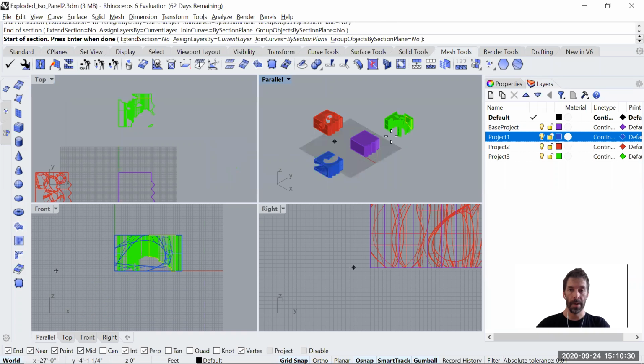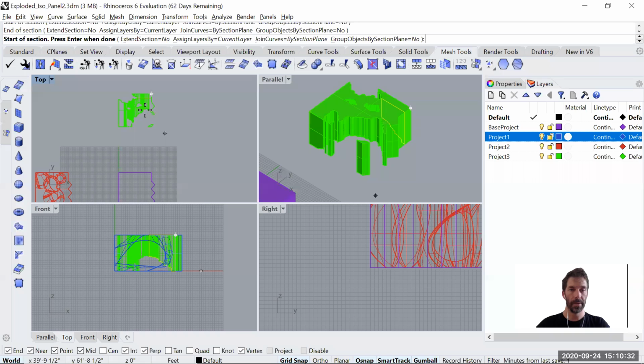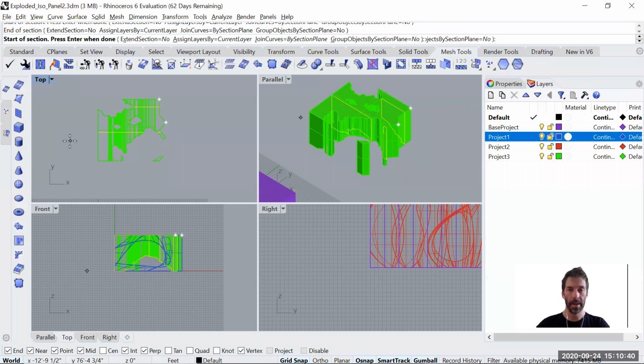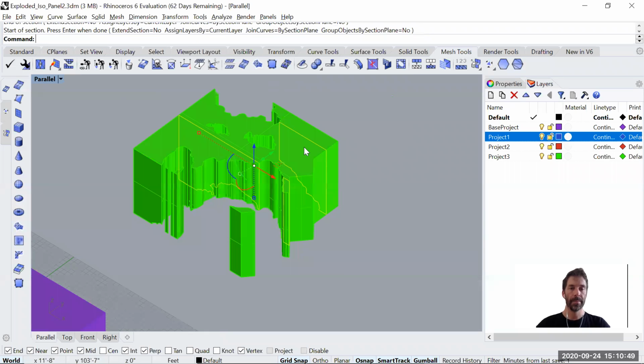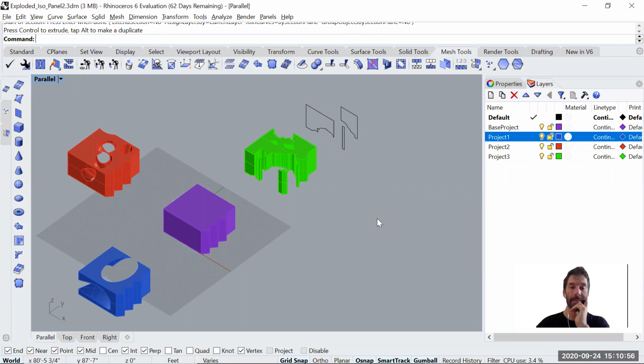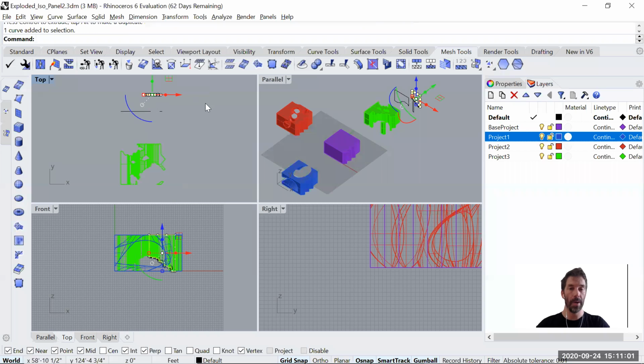And I'm gonna show you how that comes right after, no? As I create the cut and press Shift, look at the parallel view on the top right. It creates in yellow the section. You can do 2, I think it's more than enough. When you're done, you can click Enter and move the sections because they're still selected. Those are 2 sections, and I know because in the top view, I can see one here and the other one there, no?